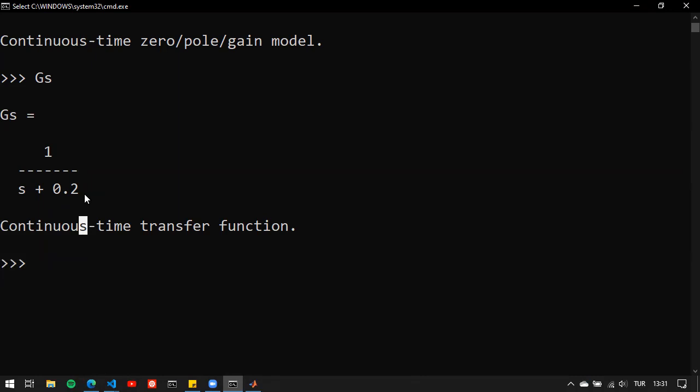Another way of looking would be the following. We could also use a PI controller here, but only using a PI controller, we would not achieve that much because we have a zero of the PI controller and we will have a second order closed loop. But by using a PD controller before we use a PI controller, we alter the system and get the best out of it.